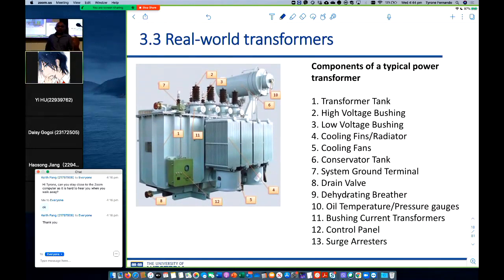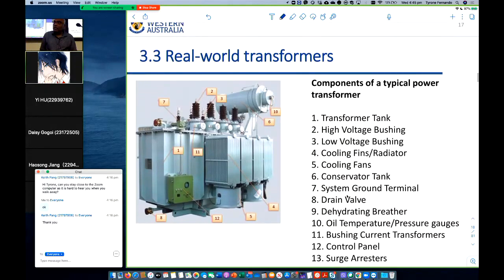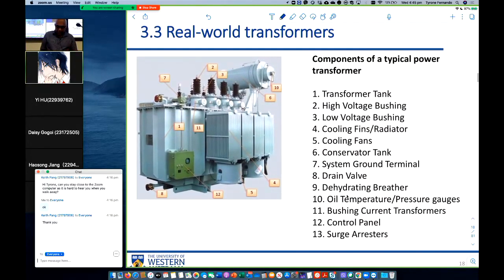So we talked about reflecting impedances from the secondary back into the primary by using the turns ratio squared. We've looked at an example there. We've looked at why it is advantageous to step up voltage before transmitting power and then step down after the transmission line before consuming. We can minimize the I squared R losses. All right, so that's the ideal transformer. Should be fairly straightforward. You should be able to follow the lecture notes and the calculations that are done there.